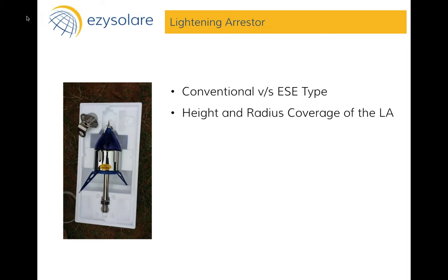Also, ideally speaking, you should have redundancy. According to the standards of design, you should have redundancy, which means that wherever you are having one earthing pit for one kind of earthing, you should also have a redundant second pit. That makes it two DC side pits, two AC side pits, and two pits for lightning arresters. This is often not followed in Indian circumstances, but this is what the standards say. The third thing is also about how do you determine the size of the earthing strip that you need to put.